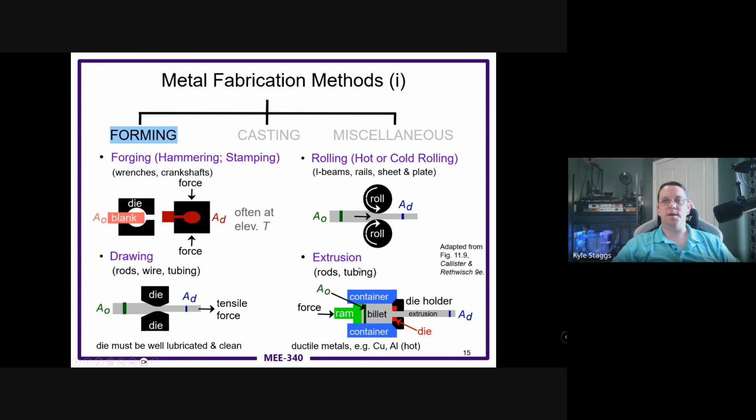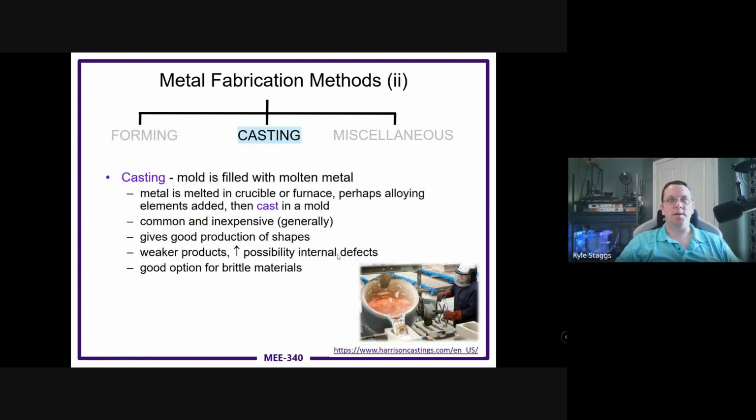Alternatively, sometimes someone will extrude a shape, or they will roll a sheet lengthwise and then weld it. That's another way to make tubing. A lot of common exhaust tubing is made that way. It's rolled out into sheet steel, then formed into a circle by rolling, and then welded along a seam, which is fine for an application like that where there's not a lot of structural importance to it. It's just a pipe to carry some gas to some other place.